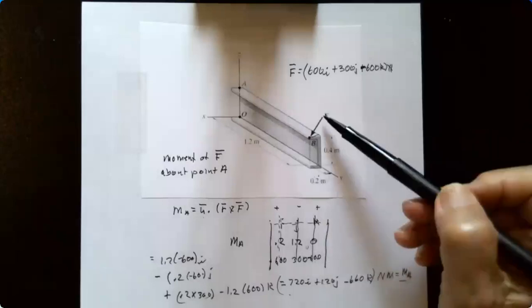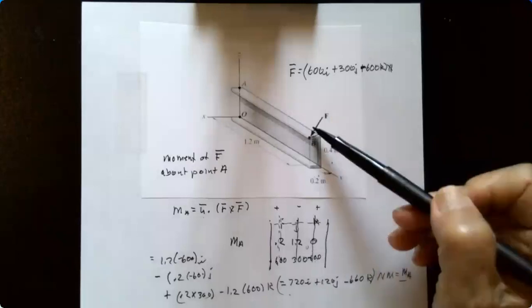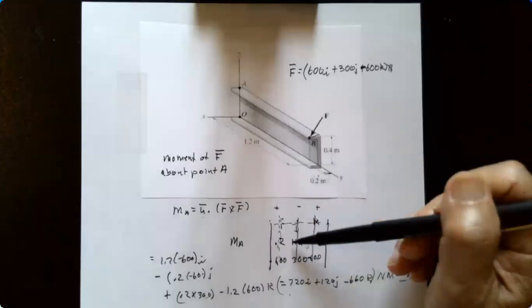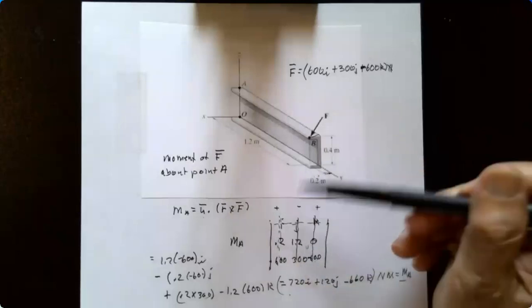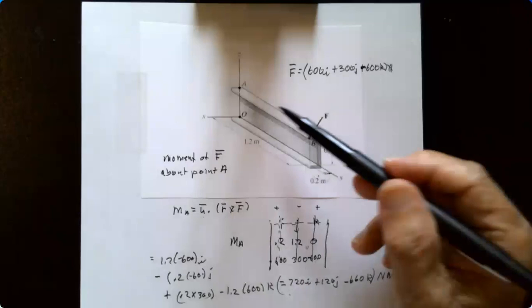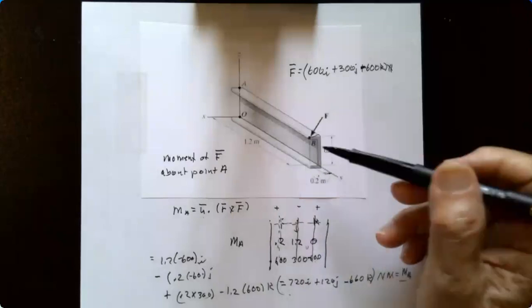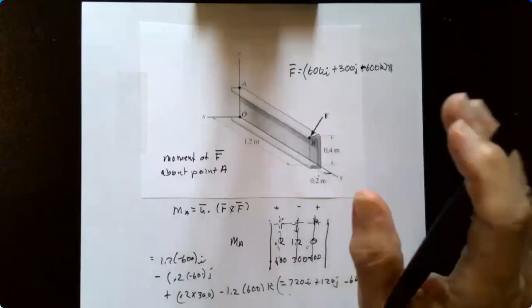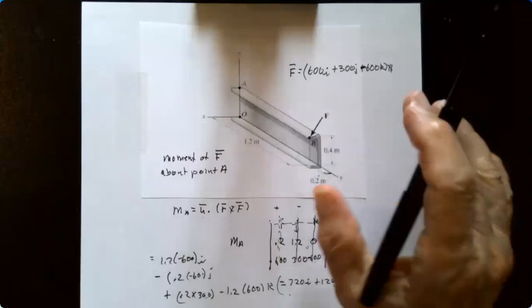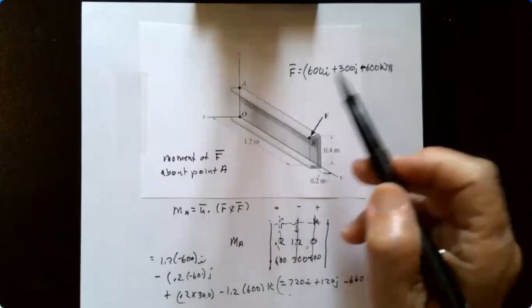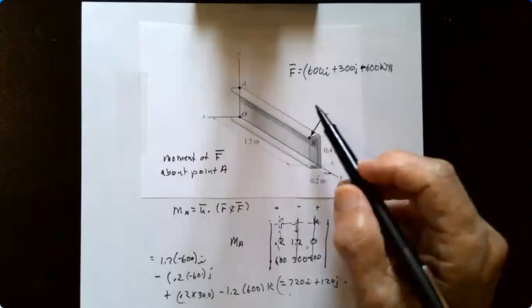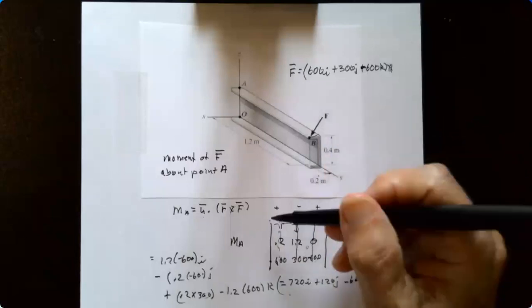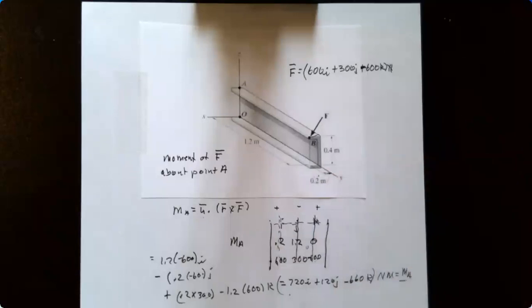Using force, Cartesian vector, position vector, this equation here, times the unit vector. And again, we're in the IJK axis system, unit vector. It's not a specific axis we're looking at or a line in space, which would be different. We'd have to get the unit vector for that line in space. But in general, then it's just the IJK components that we're looking at.